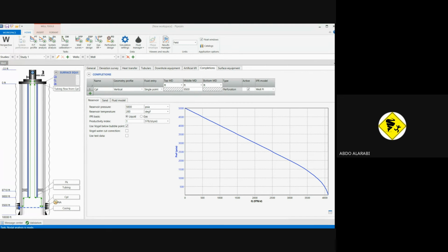If you need pressure, you will show the pressure. Yeah, I got it, from profile results. Your profile, yes, profile. There we can get this chart, which represents the pressure as a function of the elevation. Of course, we can't change the pressure. For this example, in this case, this is the pressure profile for the well. This is the pressure losses through the reservoir.